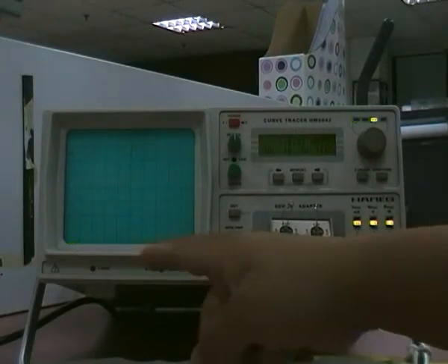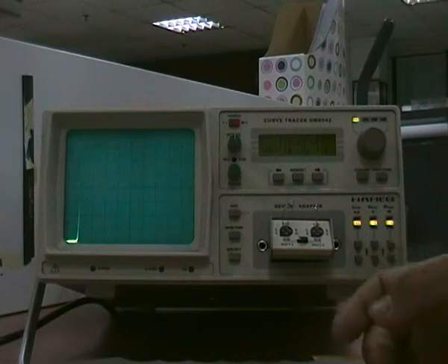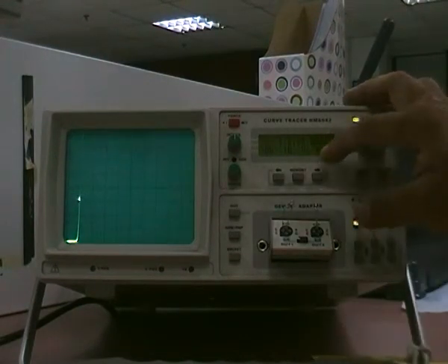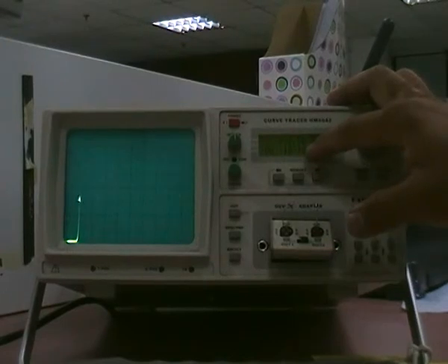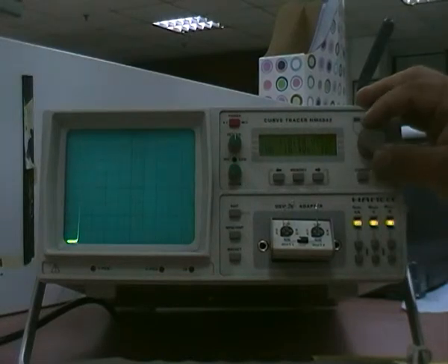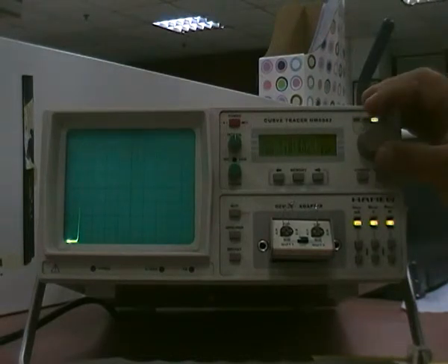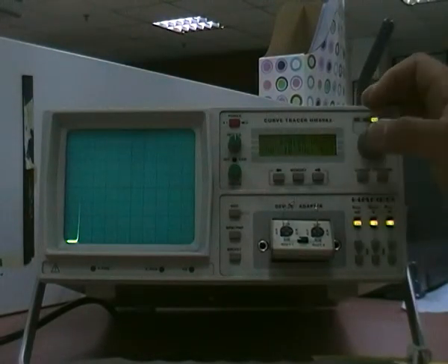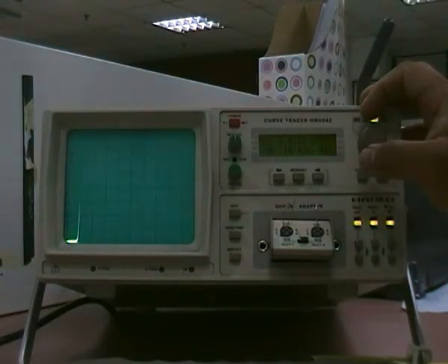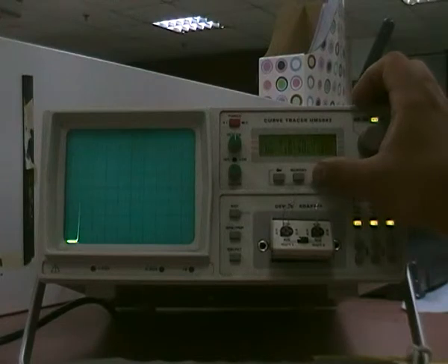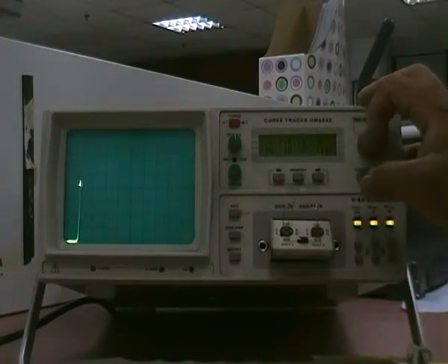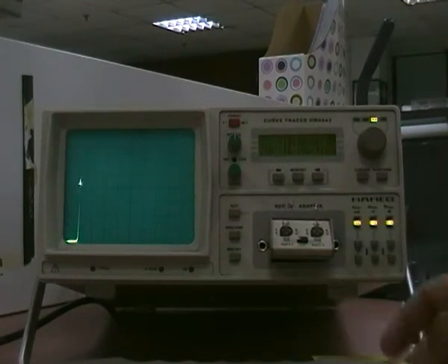I can increase the voltage. Now it gives you a warning. If I measure the voltage here, this is 0.78, already turned on. Still will do the same thing. It's already on, off, on. Now there is 0.79 volt across the diode. The current that flows through here is 10 milliamps. So now I'm stressing the diode.